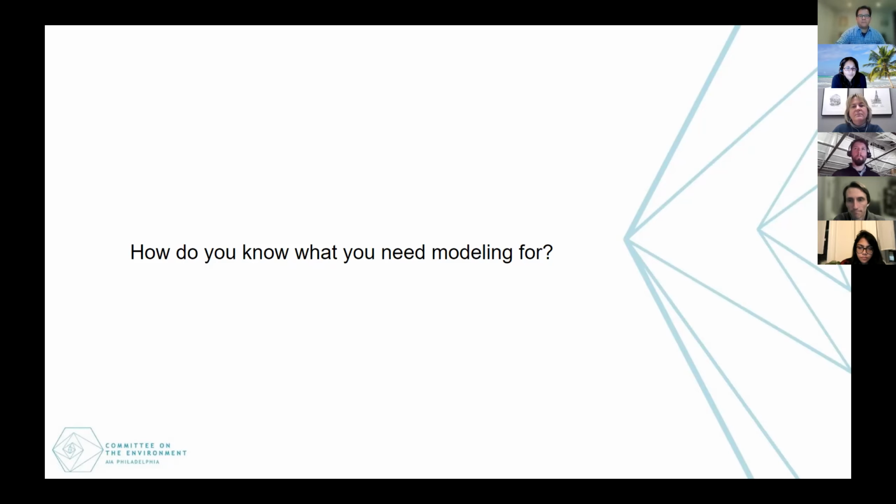Awesome. So we did have another question come in from Brian. It's for Heather, Kit, or Ryan. How do you resolve early decisions such as the relationship between floor to floor height and ceiling height and associated pressure loss and fan energy when you have pushed the floor to floor too low and the ceiling height too high, assuming a drop ceiling? Perhaps there's a continuum from straight runs to Swiss watch. What are the factors used to measure this system complexity?